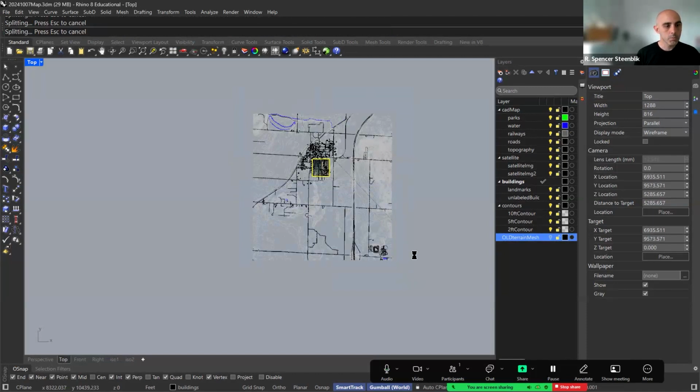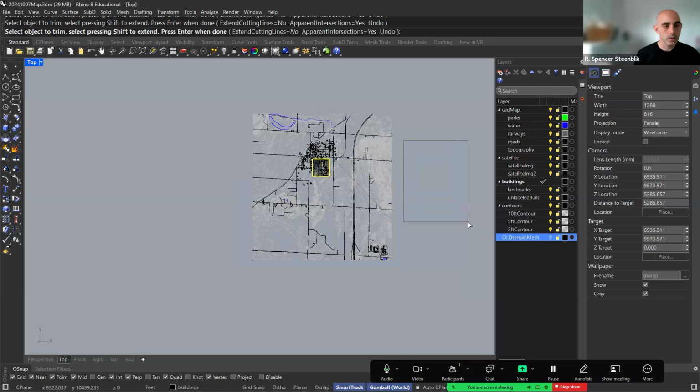And you'll notice that I'm using the selection with the dashed line. If you select from top left to bottom right, you get a solid line. The other way, you get a dashed line. And basically, it's an exclusionary selection process or an inclusionary selection process. This includes anything it touches. This only includes things that are fully enclosed in it. So I can use that to actually delete objects that are outside of those things.